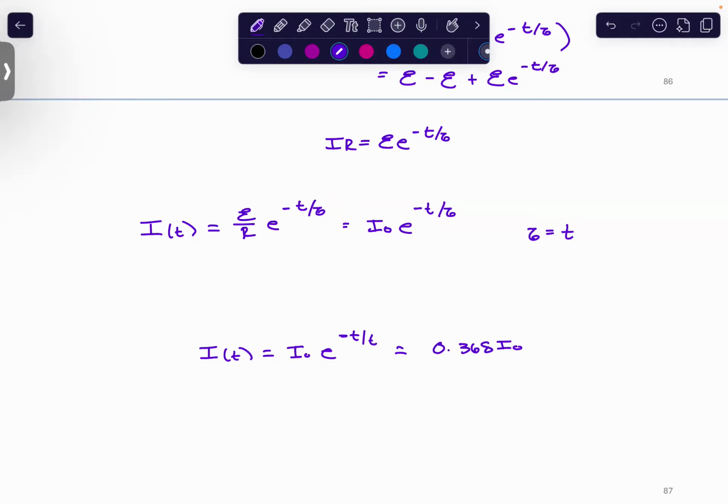It's when the time that you're charging the circuit. The timing constant is R times C, which is the circuit. And then when your time t actually equals your R times C, that's when you have a point where t equals the timing constant. And so you'll either have about 37% of your original current left, or about 63% of your capacitor charged.